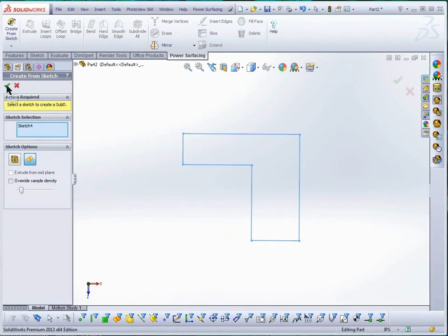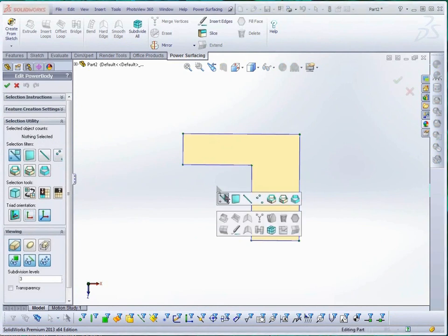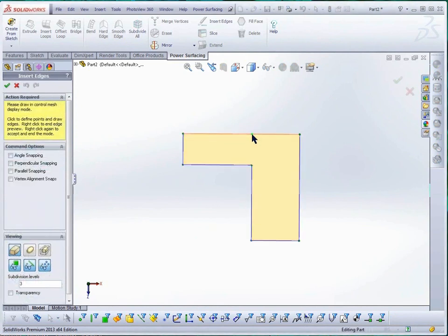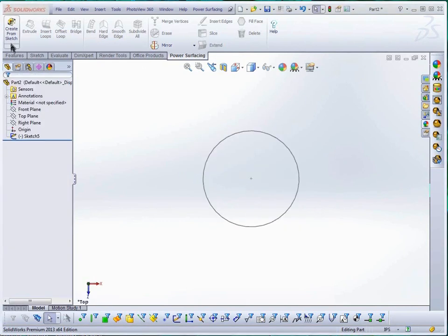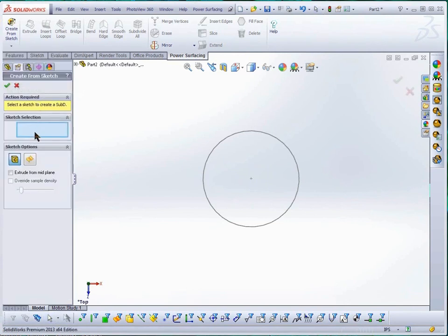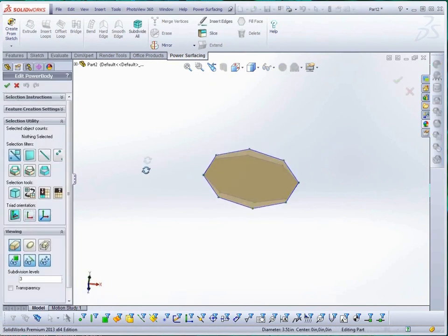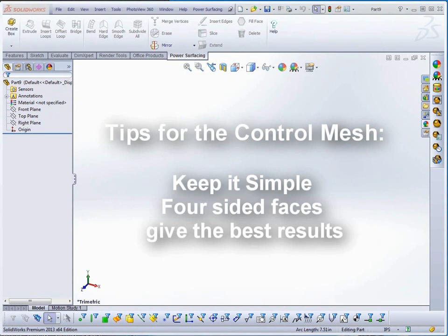The other sketch option is to use the sketch to create a surface. This more advanced option will allow for more than 4 sides, but may require you to manually retopologize the resulting surface. Curved edges will be recalculated based on sides per 360 degrees, so once again, keep things simple to start. Whatever method you use to start your sub-D, you are defining the control mesh that is used to create the subdivided model. Defining dimensions, location, and orientation is only a starting point.